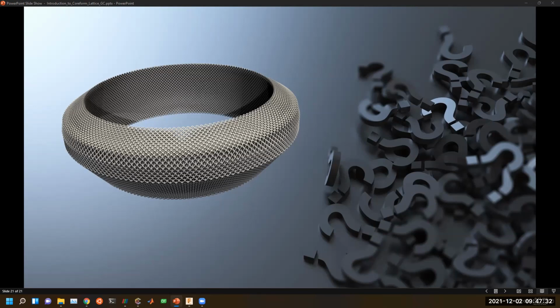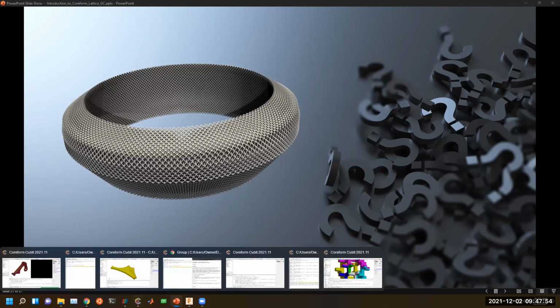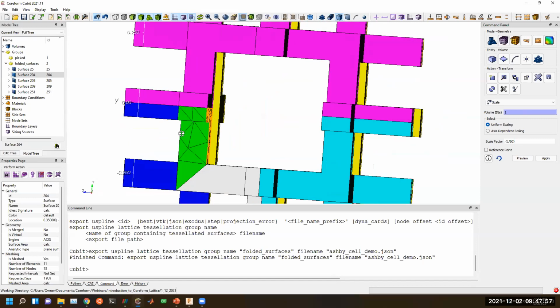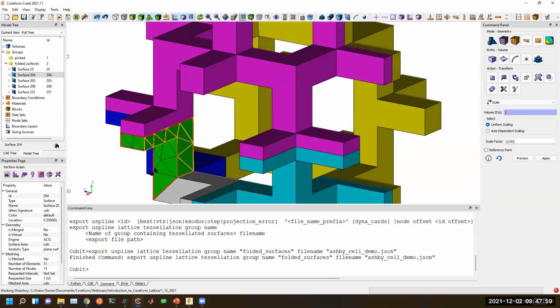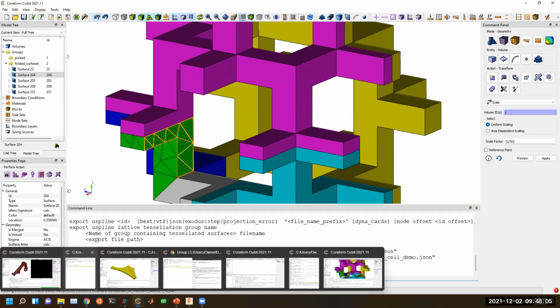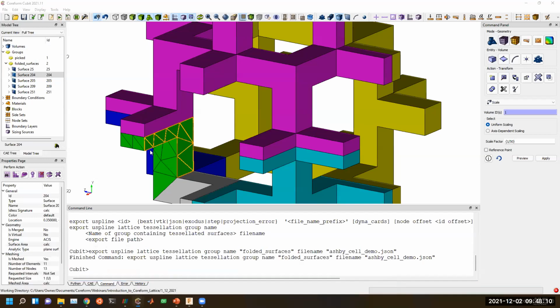We got a question from Ron. Will you be able to use the lattice as a geometry that could then be meshed and exported to an FEA solver like Abaqus? So at least right now, the lattices that we can export are exported as triangle tessellations, and they'll inherit that tessellation from this tessellation you see here. Now, once you have, say, one of these solids, let me see if I can actually import maybe a demonstration here.